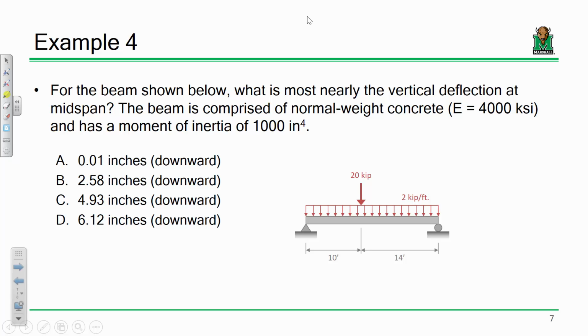All right. Here's what I'm going to tell you, and I can post a video on this particular example in a little bit, but there's really 2 things that you need to keep in mind. You could use the unit load approach, but I would highly recommend against it. Instead, what I would do is go to the beam design aids in the manual, referenced earlier, for determining beam deflections for these cases. The only thing I would say is just make sure you convert everything to consistent units, and I'll post a video on that later. But they're basically plug and chug.